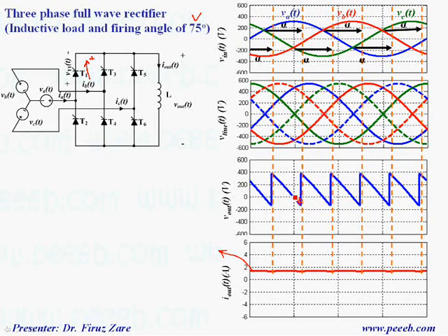But the point is that when we turn on another thyristor, because the other phase is greater than that phase, the voltage across this thyristor becomes negative. So that's why we turn off this thyristor once we turn on either this thyristor or that thyristor. That means natural commutation.